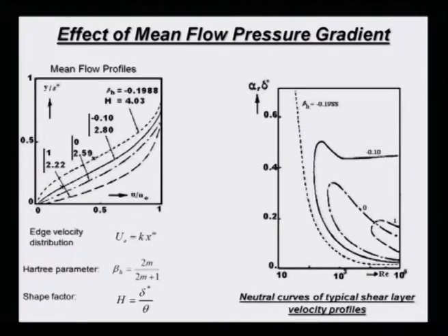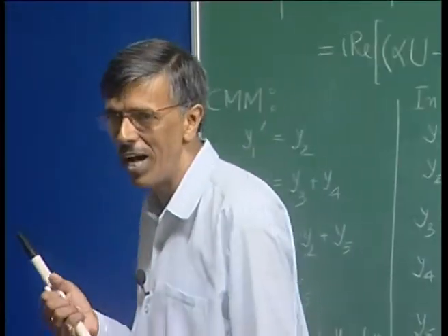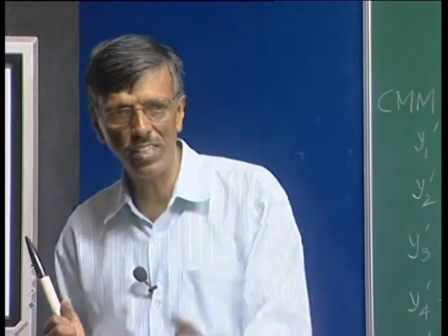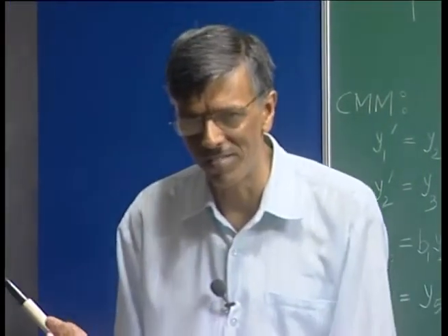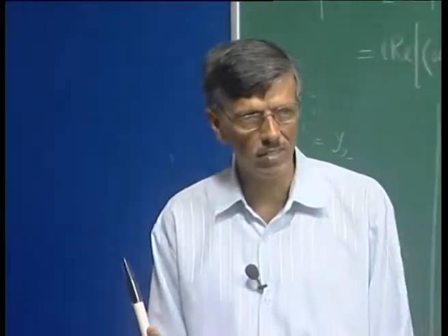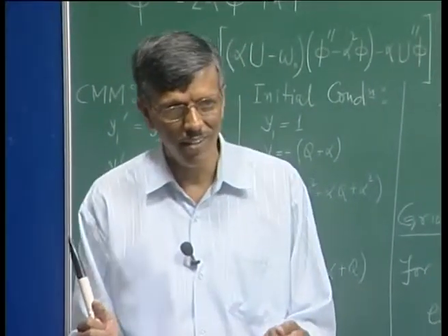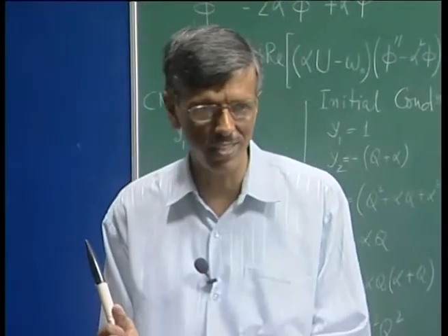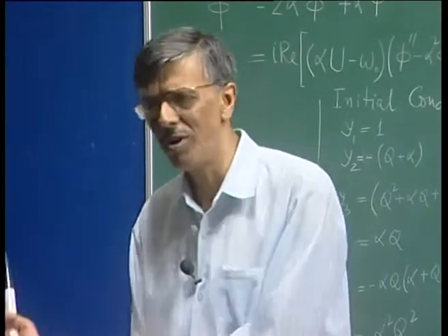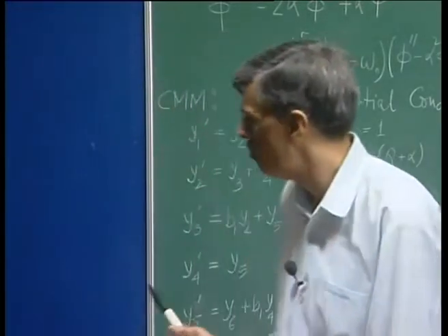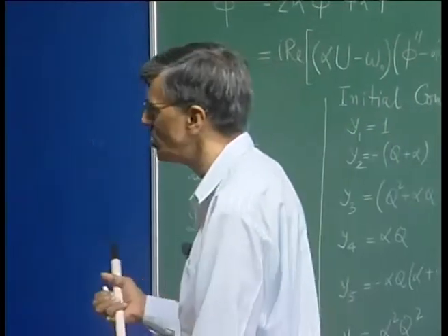And now, in actual geometry, what will happen? You are going to get all kinds of pressure gradients. So, think of the aircraft wing design. I would have at different stations different pressure gradients, right. It is not going to be a flat plate. Of course, you calibrate and gain confidence from a standard geometry and standard result, that is the Blasius profile. You are happy that you have done it, but now if you want to use it for an actual practical scenario, then what you are going to get?